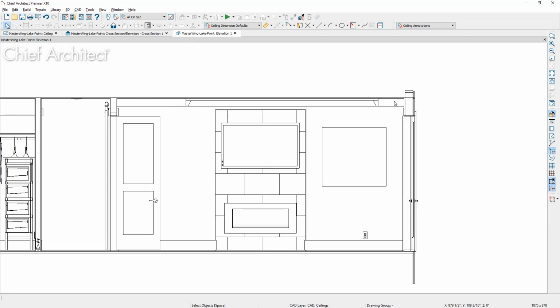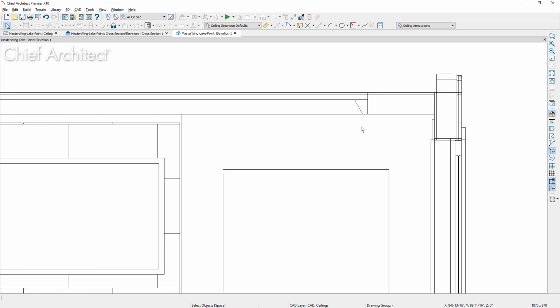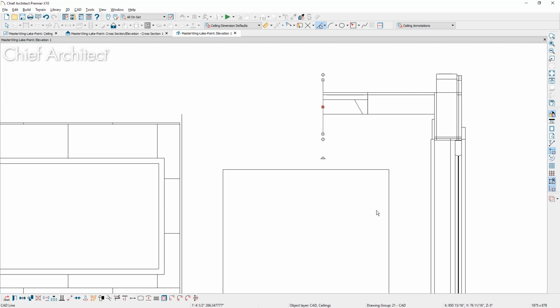Let's zoom into the section that we're interested in, and what I'm going to do is draw a line in here, and this will act as a cropping line in this area. Let's go ahead and choose the line while it's highlighted, and then you'll find an option down here in your menu that is a trim option. That will allow me to now trim all those extra lines.